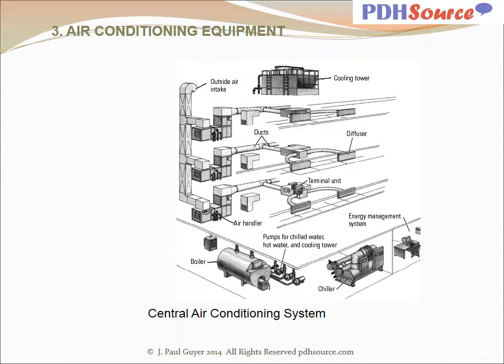So you've got in the basement or in the mechanical room a machine called a chiller that is producing cold water, and all of the refrigerant cycle items are in that chiller. And then you have a boiler which is creating hot water, and the boiler is just a big tank with a burner heating the water in it.